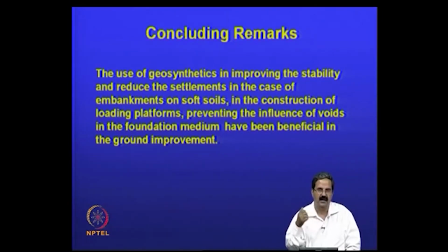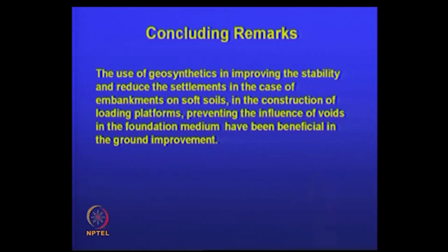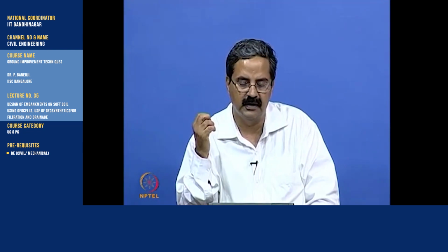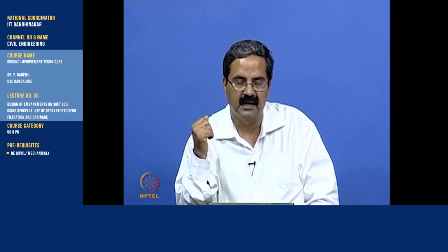We have discussed internal stability and external stability, and in the construction of loading platforms also you can use geocell foundations, and the influence of voids in the foundation medium could also be avoided, if there is some problem like that. So, this technique has been quite useful, because in many places in soft soils there is no other technique available, and this is the only technique, and people have perfected it in many places abroad and in India also.